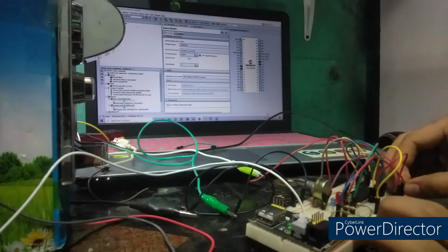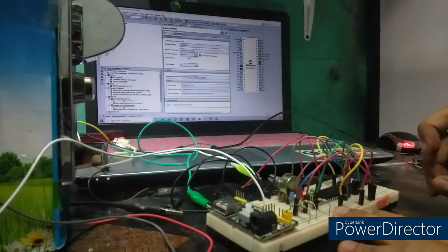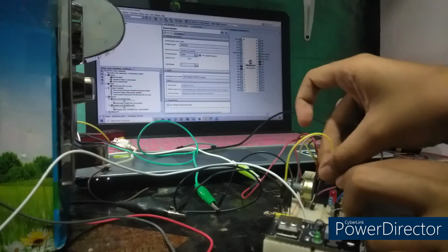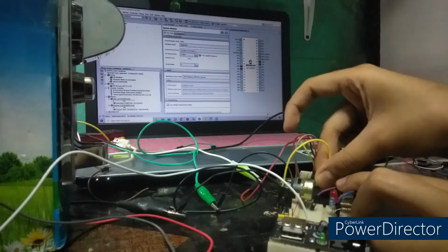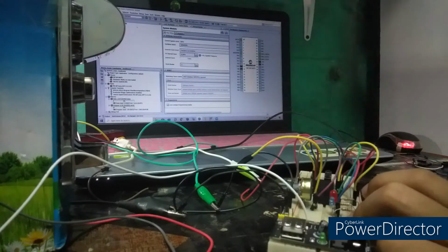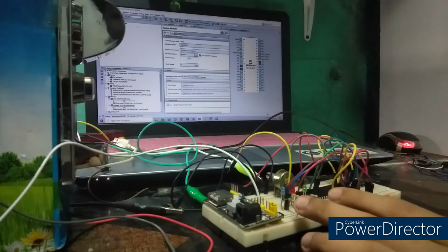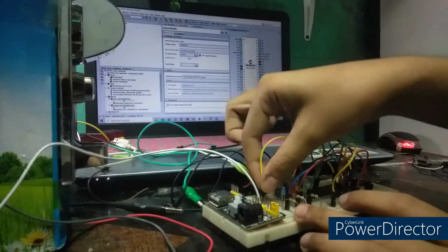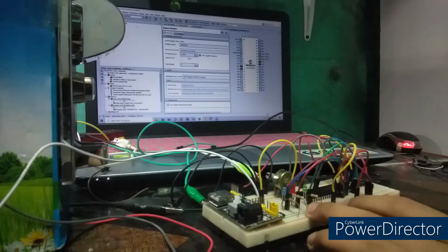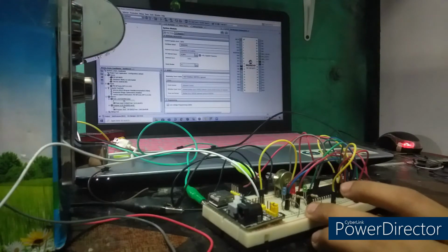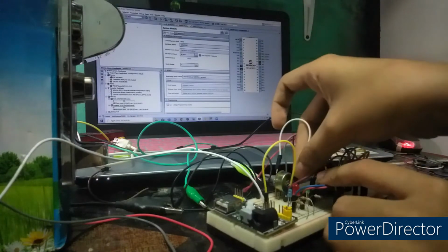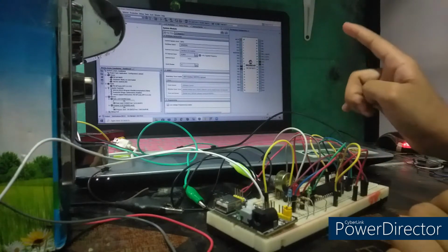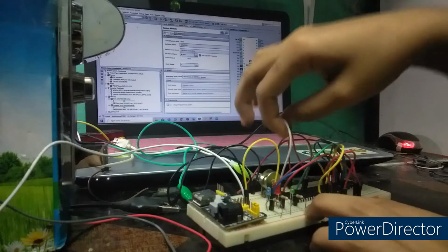So this 5 volts here of our 5 volts voltage supply, and then for the second pin, let's use a yellow wire. The second pin should be connected to the coin acceptor output, which is the white wire here, which is the coin wire from our coin acceptor. So let's connect this one, and with that, we will be connecting this second pin of the potentiometer, which is connected to our coin input, to our RA4, or to pin number 6 of our IC, which is the timer 0 clock, which will perform its function.